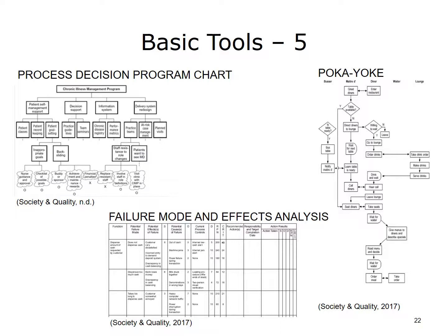Failure Mode and Effects Analysis. Failure Mode and Effects Analysis, FMEA, is a method for looking at potential problems and their causes, as well as predicting undesired results. FMEA was developed in the aerospace and defense industries and has been widely applied in many others. FMEA is normally used to predict product failure from past part failure, but it can also be used to analyze future system failures. This method of failure analysis is generally performed for design and process. By basing their activities on FMEA, people are more able to focus energy and resources on prevention, monitoring, and response plans where they are most likely to pay off.